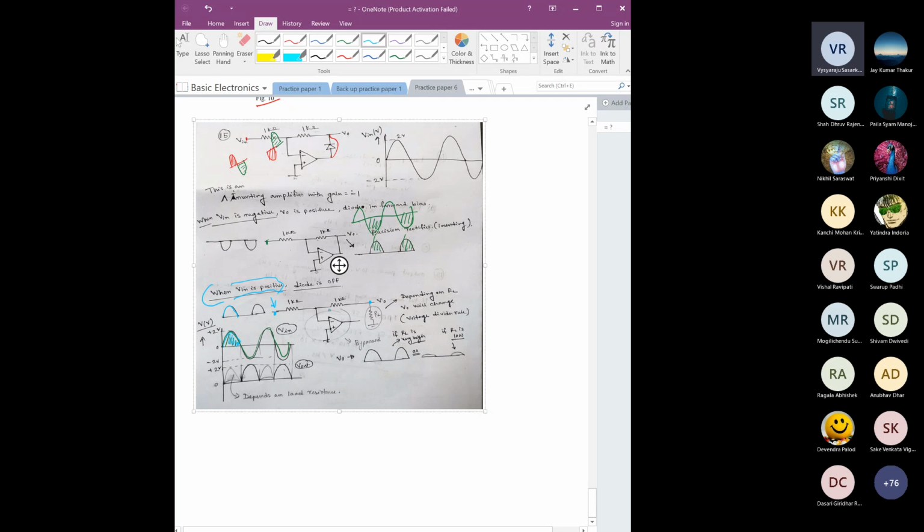Yes, sir. Right, because it is a simple resistance. Here is a resistance, and this part is connected with this. No current can flow inside the op amp. So if you have connected a multimeter here, then whatever this voltage is, it will measure the same voltage only. If it is not connected with anything, simply floating, then this voltage and this voltage would be the same.